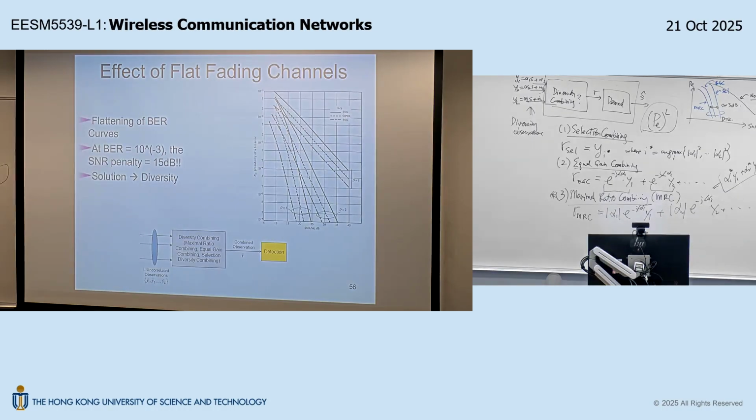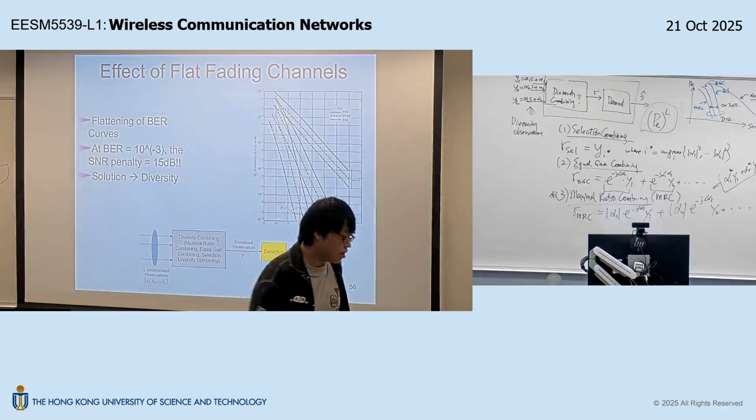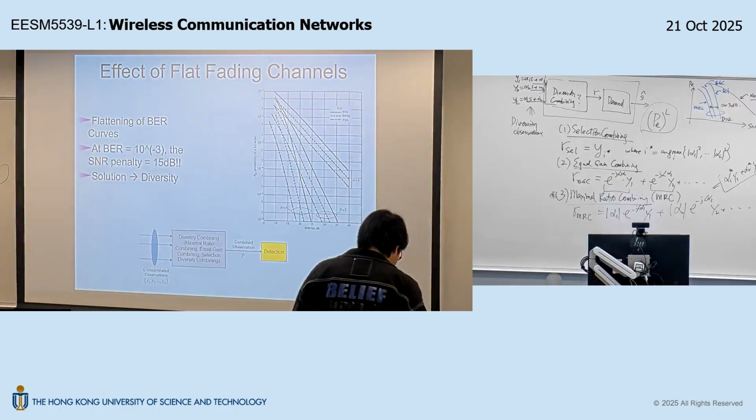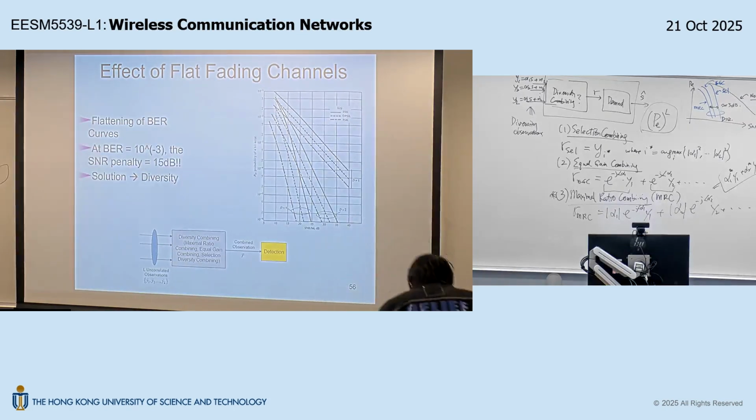But they are in RF format. Bandpass signal at 2.4 gigahertz carrier frequency. Is that okay? That is your input. Now you are the system architect. So what do you do next? Well, as I said, this is the RF signal. You cannot process RF signal directly. So similar to the baseline solution, you need to have the RF to do down conversion to the baseband.